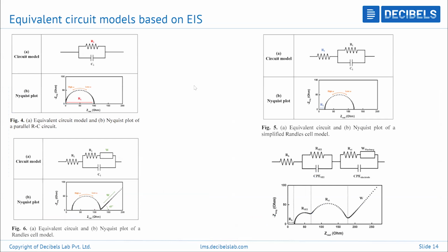With EIS-based data, how can we represent the ECM? You can see the same ECM model over here, but along with your resistor and capacitor, you are going to see some extra elements: the inductor and the Warburg. You see the inductive behavior of the cell, and the Warburg is an additional resistance that is completely related to the diffusion of your ions. That we'll see.